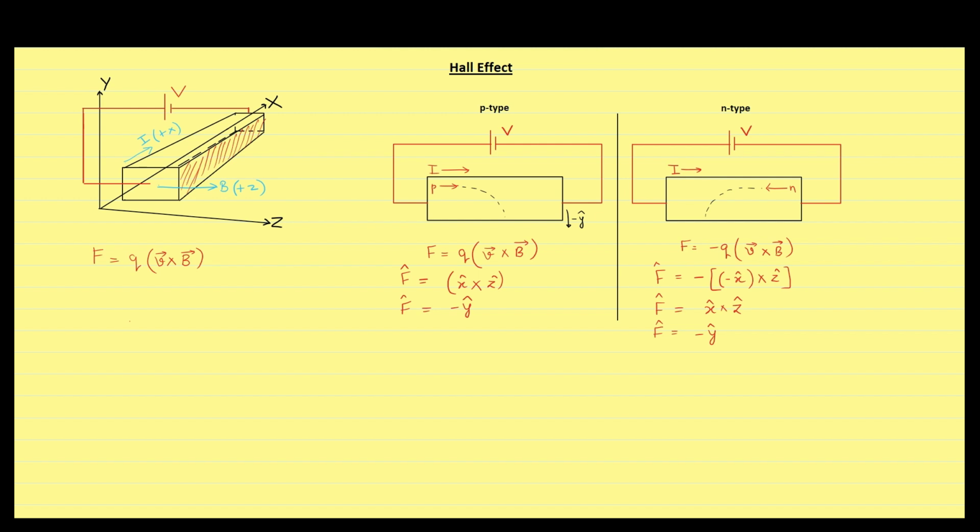One is due to the presence of external battery, and the direction of this electric field will be in x direction. Similarly, we will have another electric field which is caused due to magnetic flux density and will be in y direction. Due to this electric field, a potential called Hall voltage appears between the two surfaces in y axis.